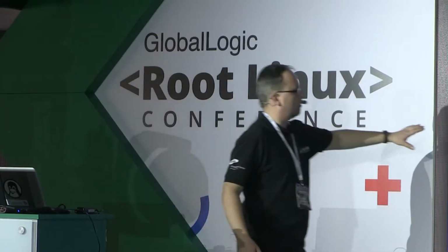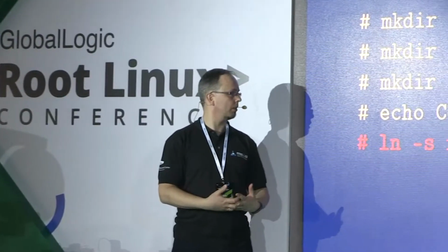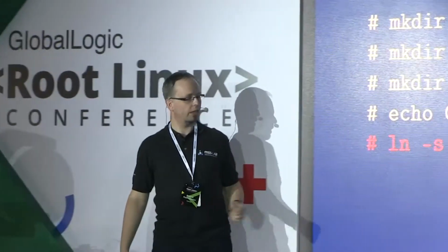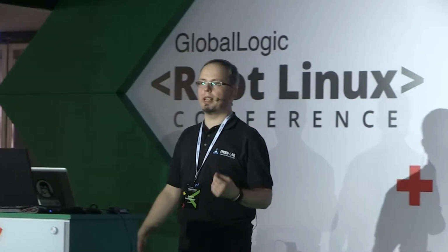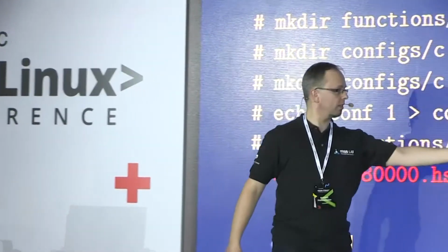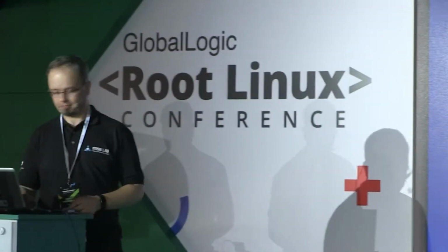At this point, the structure of our gadget is complete. It's in memory, but the gadget is not active yet. In order to activate it, we need to write the UDC name to the UDC attribute. The question is, where to get the UDC name from? Well, it's available in sysfs. In this board, there's just one. So let's use that.